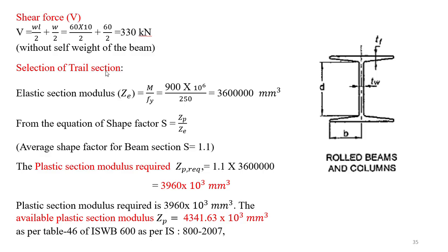After this, depending on the bending moment and shear force, I am going to take a trial section depending on the elastic section modulus.